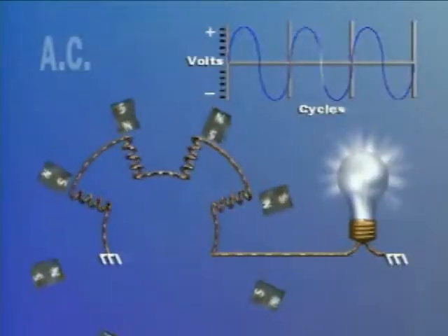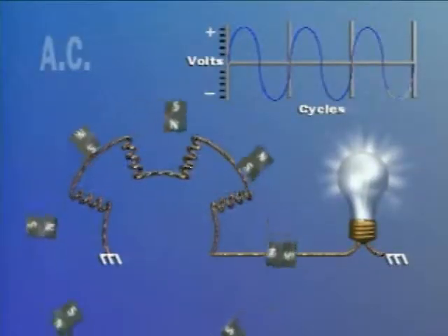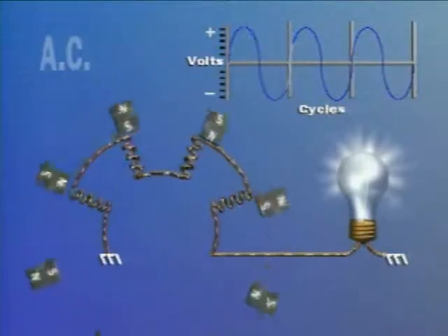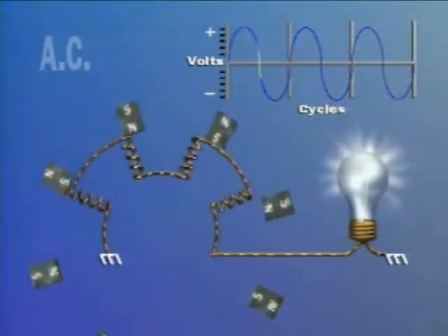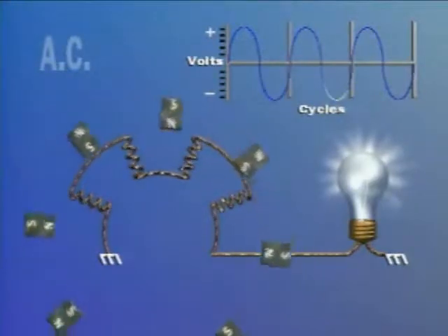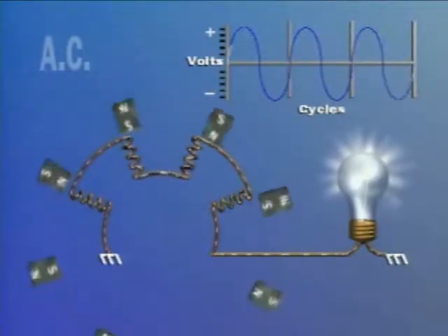This type of system is commonly used as a lighting system on a piece of equipment. However, it cannot be used to charge a battery. Charging a battery requires direct current, or single direction current. A minor modification will be necessary to convert AC current to DC current. This modification is the addition of a rectifier.